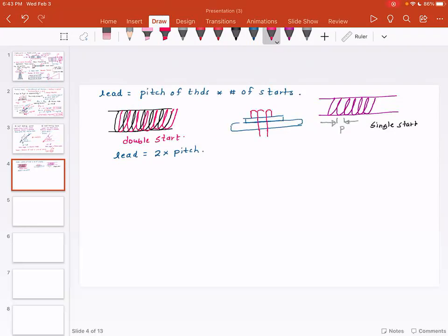What you do is you drill the hole, and then you have this bolt that is going in, and then you add a small nut on the other side. So you have the bolt, you have the washer, this is the base plate, and then this is the nut.